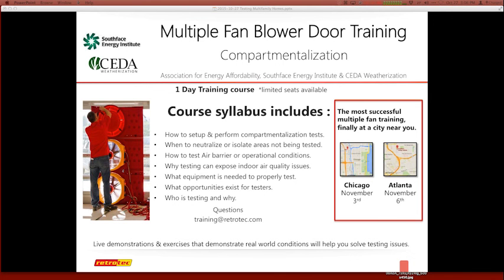There was also a question about how we seal above the door closers. In some cases it's easy to take them off. With the aluminum frame and cloth, the only real option with door closers is to take them off, or to put the fan in another part of the doorway where you can get the frame to grab hold and get around the door closer. The hard panels, of which we have 2 or 3 different models, are quite different because you can bring the hard panel up to the door closure and then use a piece of grill mask or tape to tape over that hole. So the hard panels are much faster for testing large buildings, which is the reason why we use them.